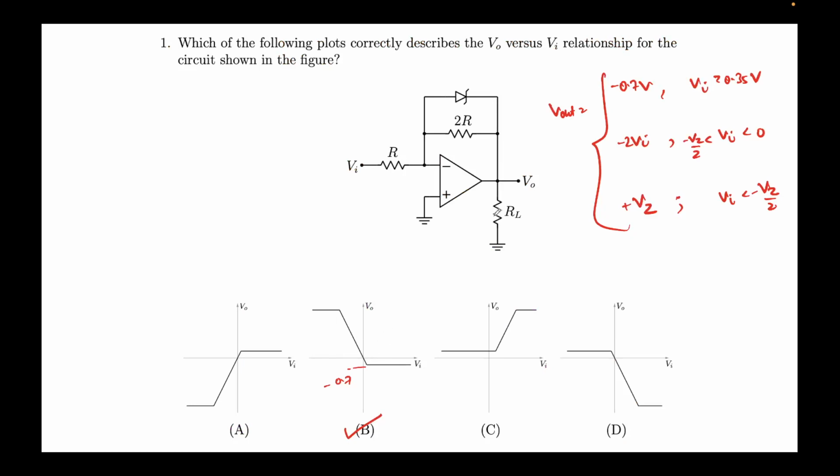So just keep this in mind. You just have to put the conditions on this diode D, and you will identify three cases. You can clearly see, just like a comparator graph, we saw two saturations in one linear region. It's the same case over here. You can also see that the voltage is clamped at some voltage Vz. This is also acting as a regulator. The voltage cannot rise above Vz.